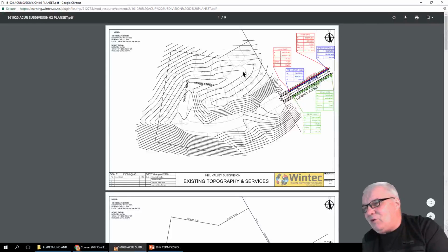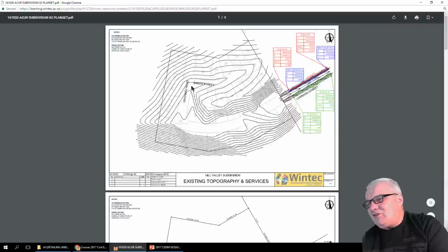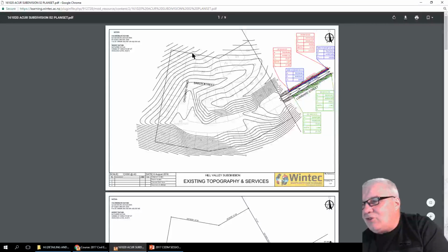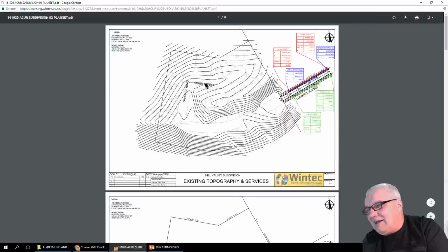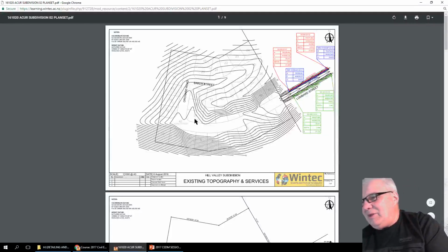But then when I came to want to get drainage and stormwater out of here, it became a bit tricky because I had a low spot in here and I had to get obviously my drains and pipes. So yeah, that's something I hadn't sort of anticipated when I did my layout and then did my surface, and then I had to work on that surface. If I was doing things again, I'd probably try and get this coming up more harder, or more quickly.